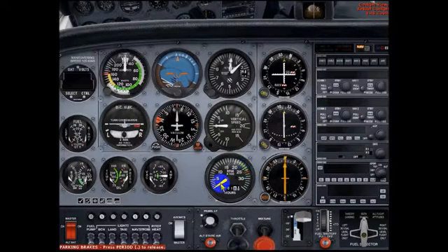Let's go back into our aircraft and let's look at the panel. So this is our tachometer. This measures how fast the engine or propeller is rotating. You see RPM times 100. So this is 500 RPMs, 1,000 RPMs. We're just basically adding 2 zeros to the single or double-digit numbers. As the aircraft is rolling, we typically idle at 1,000 RPMs. And then again, green, the normal operating range. 2,700 is right there.